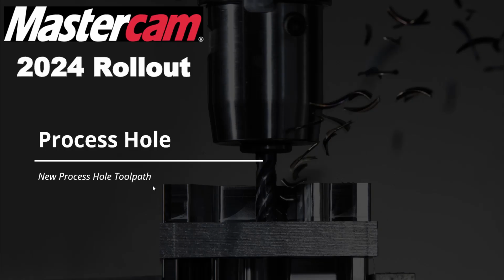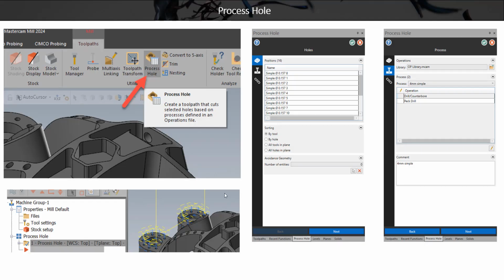The first thing we're going to take a look at is that there's a completely new toolpath in Mastercam 2024 called Process Hole. For starters, this is not found in your 2D mill category by the other hole making toolpaths. It's up in the top of the ribbon bar next to the toolpath transform. It is also using the new panel interface for the toolpaths. We've seen some toolpaths done in this interface, specifically in the lathe product, the B-axis turning and the custom threading toolpaths that were introduced in previous versions of Mastercam.